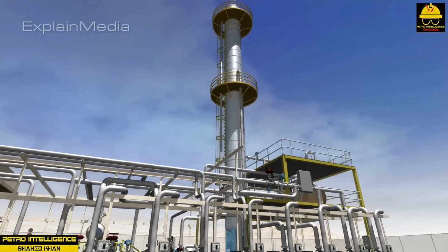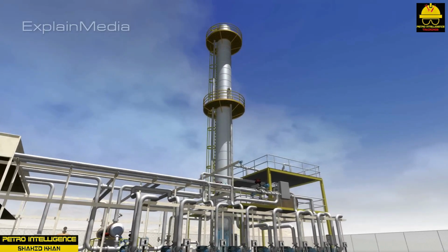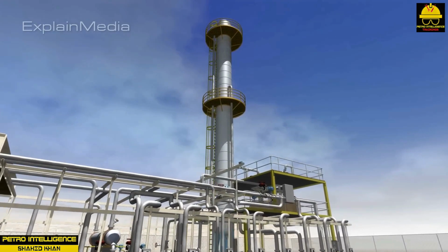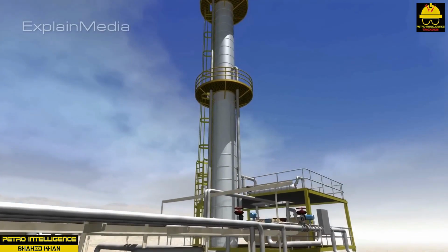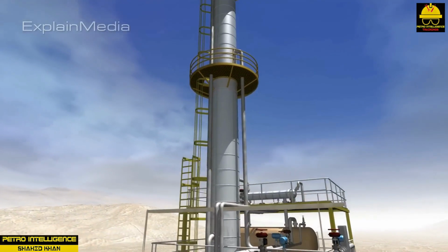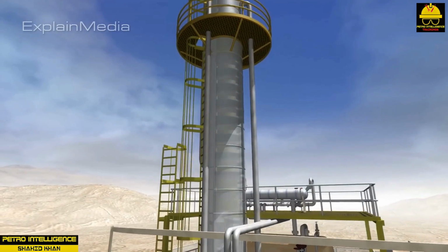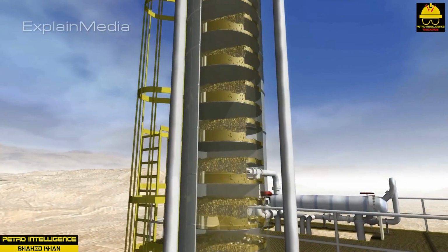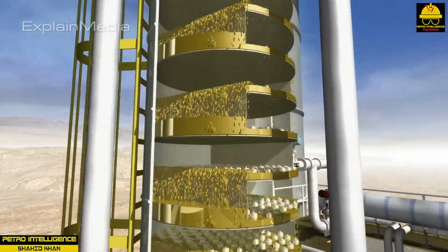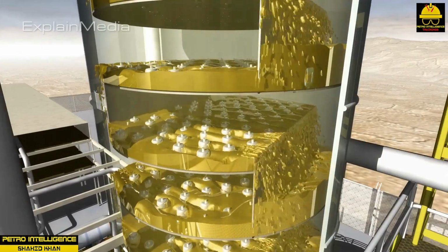As vaporization occurs, the lighter components of the mixture move up the tower and are distributed on the various trays. The lightest component goes out the top of the tower in a vapor state and is passed over the cooling coils of a shell and tube condenser. As the hot vapor comes in contact with the coils, it condenses and is collected in the overhead accumulator. Part of this product is sent to storage while the rest is returned to the tower as reflux.